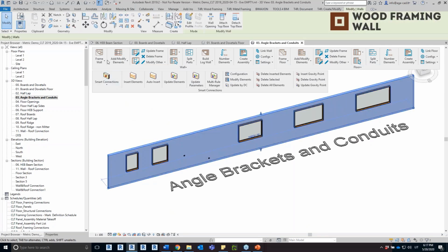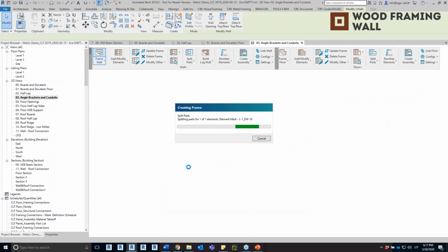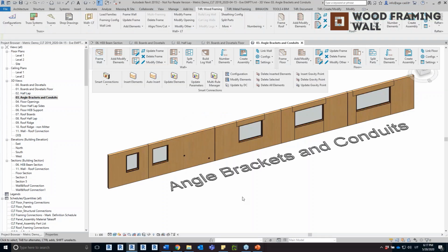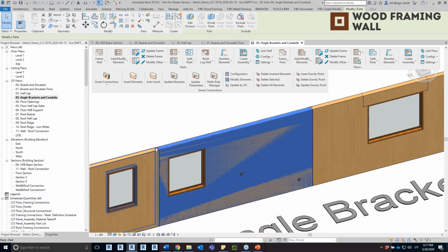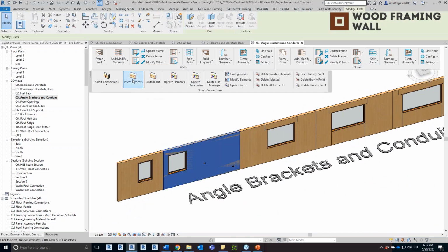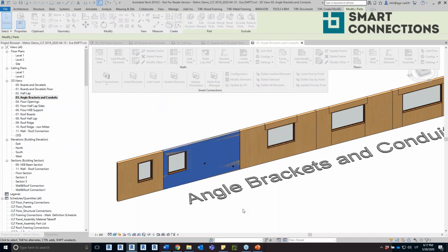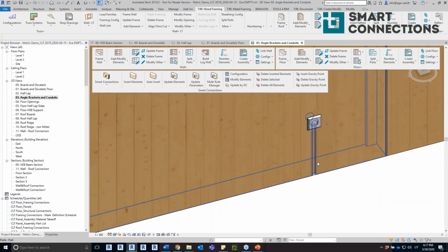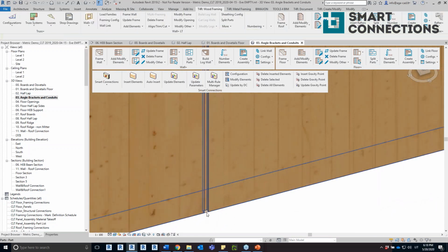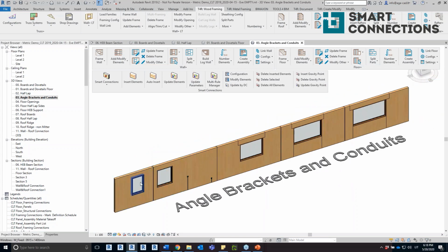Now let's take a look at another situation. So again, I will frame this wall using the configuration with the boards, but this time also I will distribute connections for the electrical fixtures. Yeah, so again, the panels with the connection board. And now I can use insert elements where I have electrical fixtures and insert the cuts for them, like this. And of course, they can be modified. All of these elements are sample ones. They're parametric. You can very easily modify the parameter values.